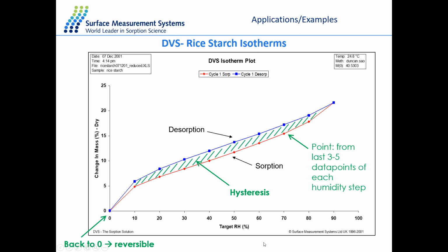Very high uptake, but also there is a gap between the absorption and desorption. This highlights the fact that there is hysteresis, which means that there is probably bulk absorption happening. Molecules have to migrate from the surface into the structure of the sample during the absorption stage, and then they have to migrate backwards during the desorption stage, which means that during the desorption, the molecules require more energy and more time to move out of the sample compared to the absorption stage.